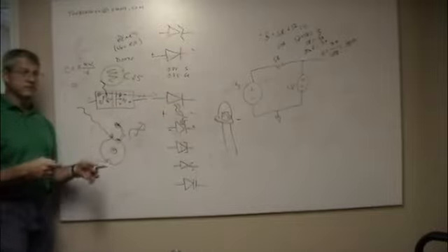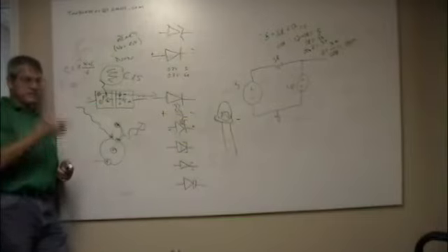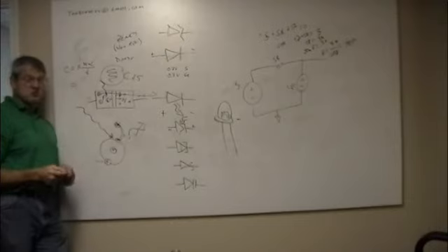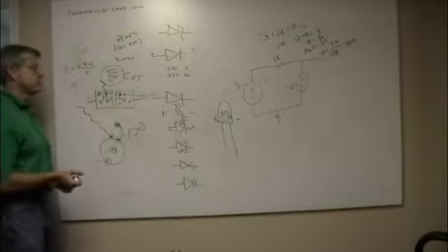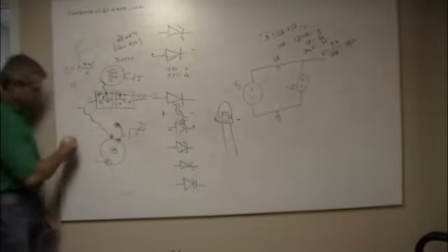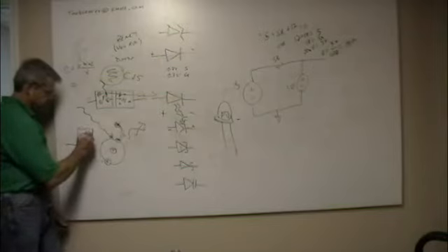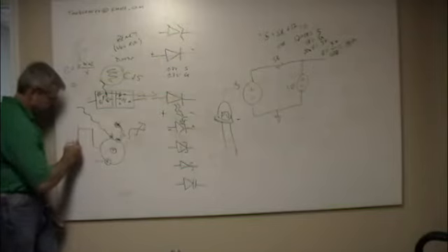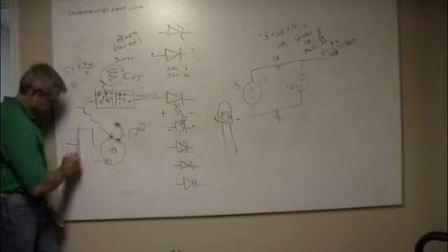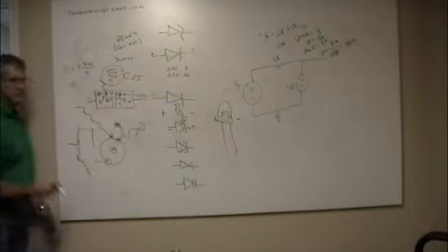But we get back to turn on times and turn off times. For cadmium sulfide, they're slow. If you wanted to flash a light and do Morse code with it, you might be able to detect Morse code at the rate that I can ham it, which would take a long time because I don't remember it anymore. The on time and off time for an LED, so if I turn it on and light comes out, that time, T on, is about 2.5 nanoseconds. It's on.